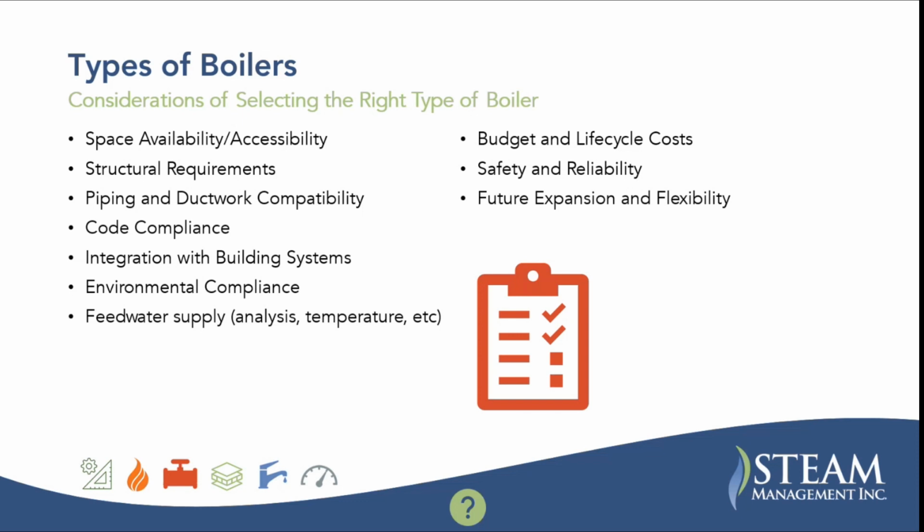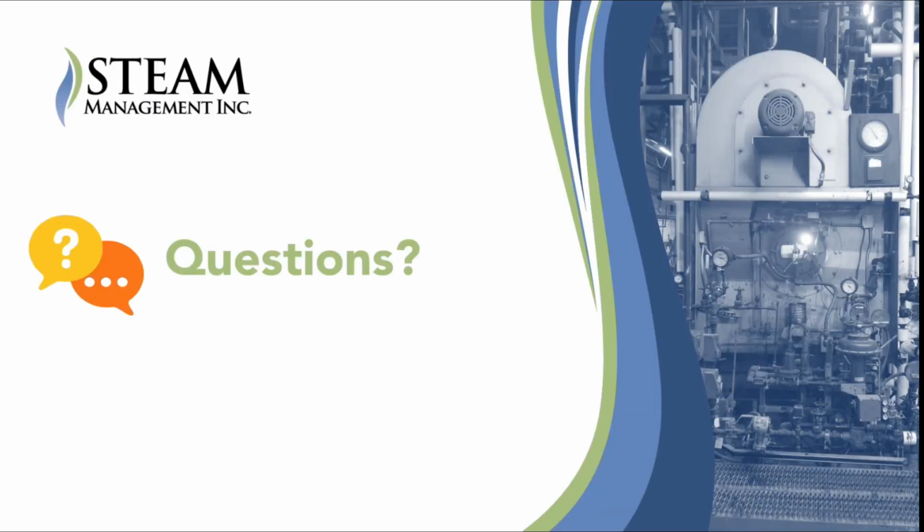So again, not pushing condensing boilers per se, but when you are considering a condensing boiler, you're often replacing 1 or 2 boilers with 2 to 6 boilers. And so how much room do you have left to expand that further? How flexible is that system? Are you operating at full load where you're not really getting the benefit of the condensing boiler at some point? So those are all considerations.